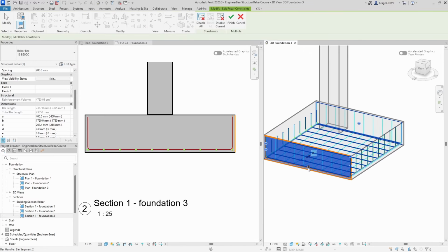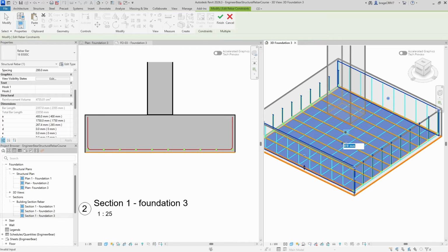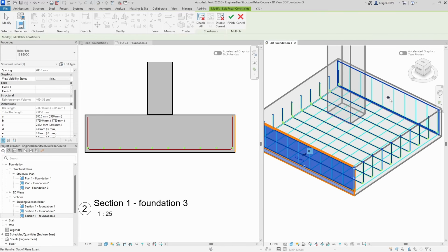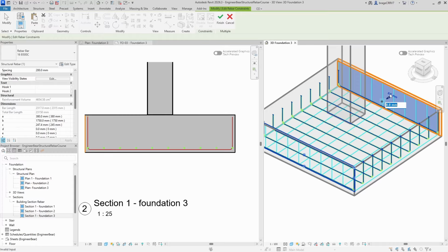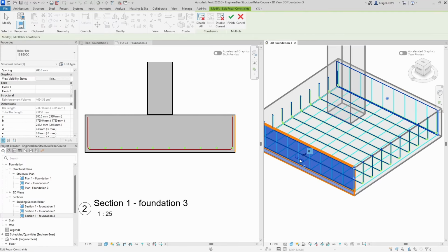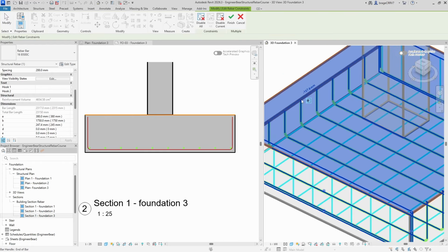So I go into the edit constraint mode and start adjusting the distance to the rebar cover. Let's set it to minus 20 millimeters, and once I type it, the rebar is positioned just above the already placed rebar. I will do that on both sides as well, so the ends of the rebar do not collide. Also, the constraints on the top of the cover must be adjusted.